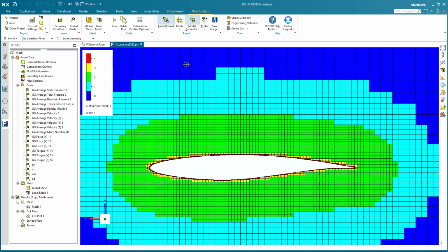We can see level 0 to 3 grid cells in the fluid region and level 4 at the walls at this stage. The equidistant local initial mesh region can clearly be seen around the wing section. In the far field, we have very large grid cells away from the lifting surface, and closer in they get smaller in the user-defined region. On the actual surface of the wing, we can see even smaller cells.